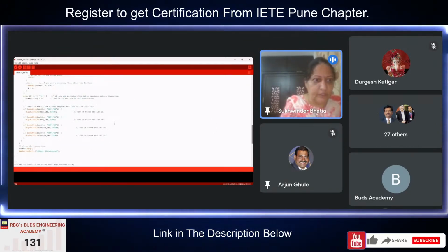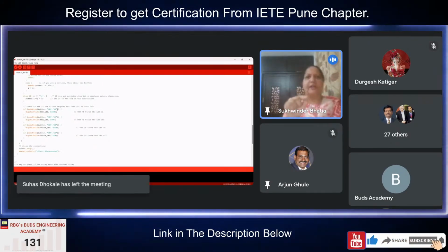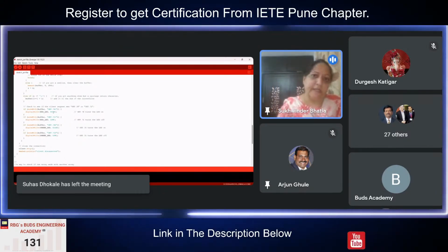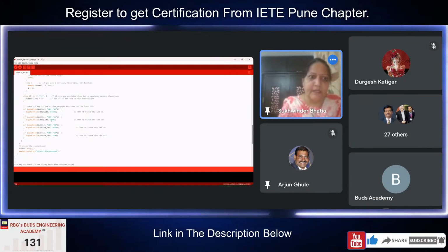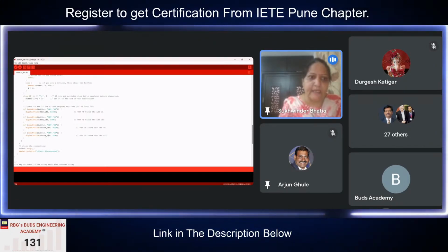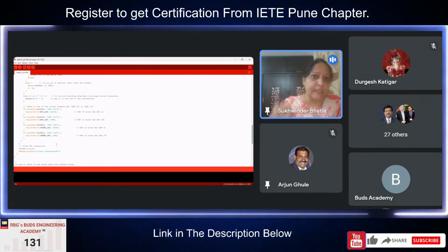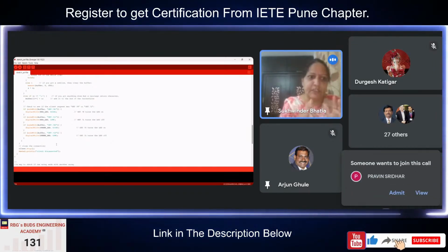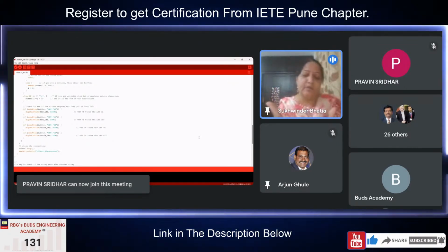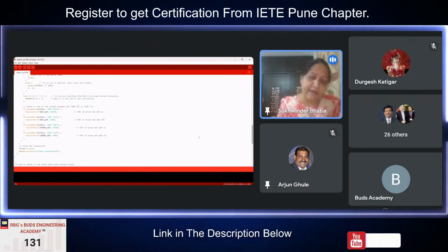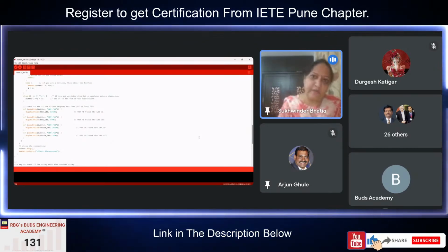And then it is just going to see on which particular web page, on which button you are clicking. If you are saying red LED high, it will send that output to the CC3200 board, input to that board that yes, you have to turn this particular red LED high. Similarly, red LED low, green LED high, and green LED low. And then it will close that connection. So start the connection, close the connection. And the client will get disconnected. Again, when you click on that button, the client will be connected again. It will pass on that information, then disconnect.